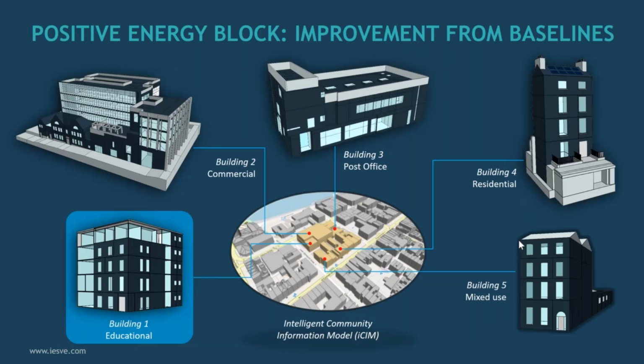So this is just a summary of all the interventions that we considered, and you can see that we considered these interventions for all the 5 buildings. Obviously not all the same interventions. For example, if you look at this commercial building here, this was already a LEED certified building, so there was almost nothing they could, or even wanted to, change in the envelope of the building, because it was just built, so they are not willing to replace anything, and it's not reasonable to do it. So this 3.6% of savings was coming from the operational side. So even if it was a LEED building, on the operational side there is always something that can be done to improve the energy consumption of the building.